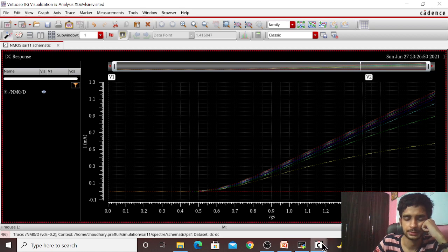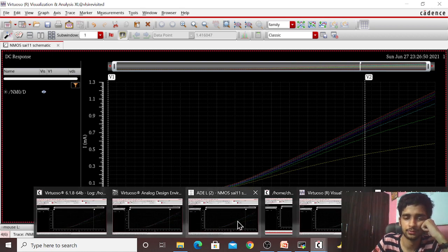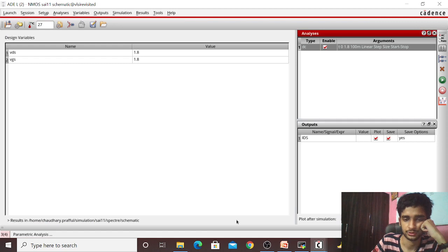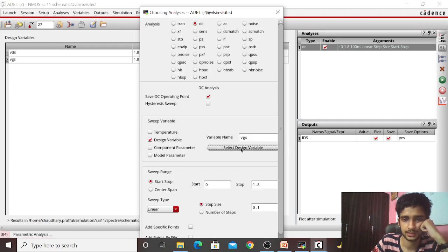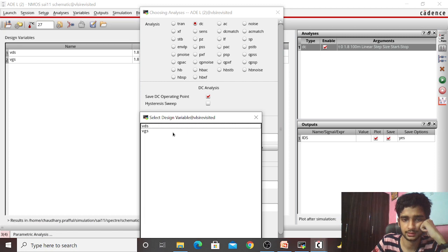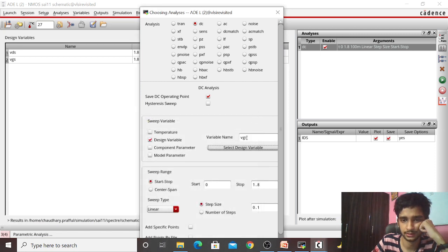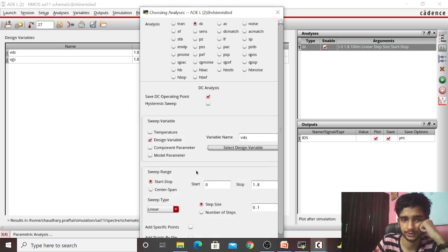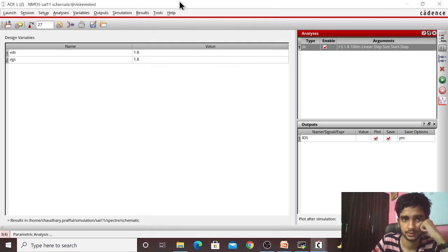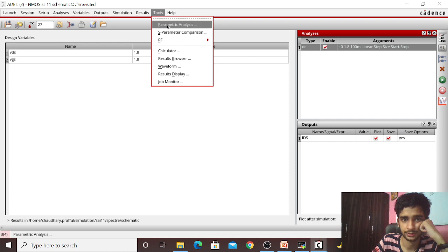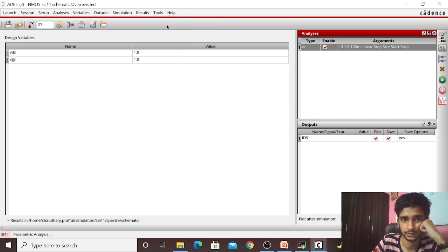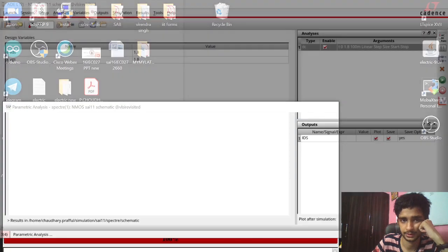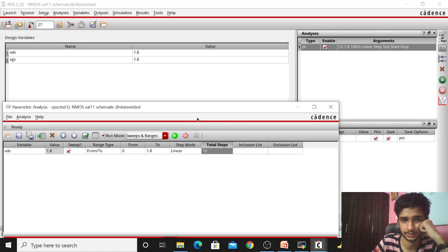So what next? Let me draw one more thing. Like try this. Just select VDS and click on enter and then enter. Just go on tools, parametric analysis. Here's the parametric analysis.